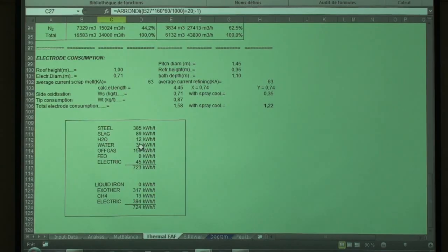But in fact, what I've seen is that the tendency is to have, let's say, slag coating on the panels, and the heat losses in the water are rather limited. The good range right now is in the range of 40 kilowatt hours per ton in the panels. Very bad furnaces are running with 80. Good furnaces, I remember even 35 is a good furnace.